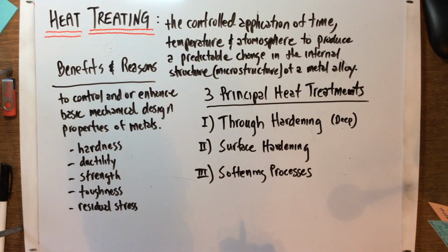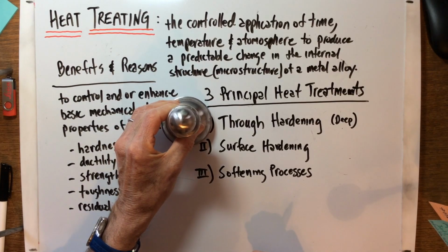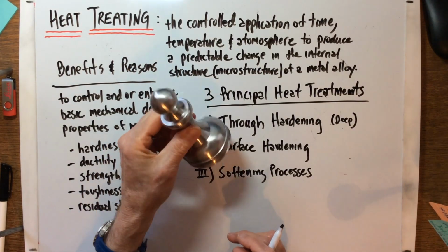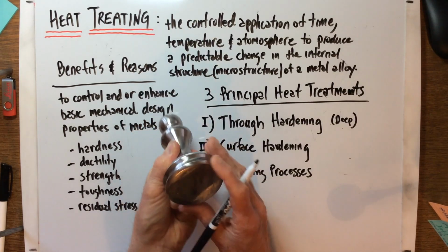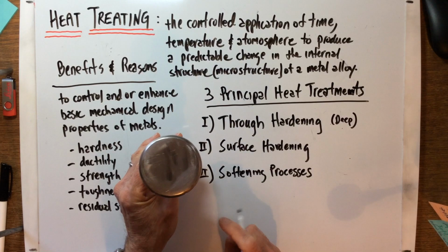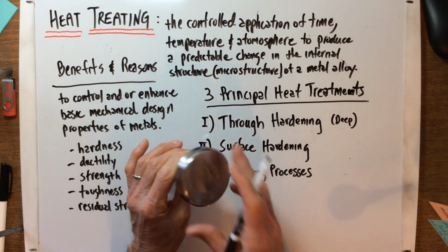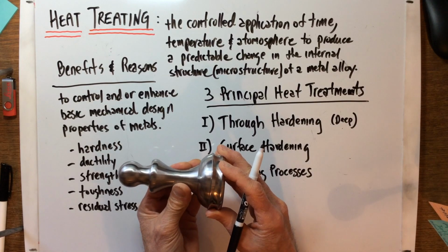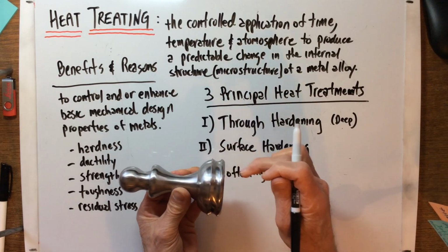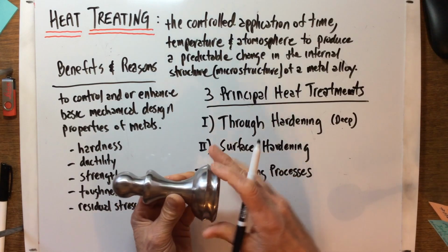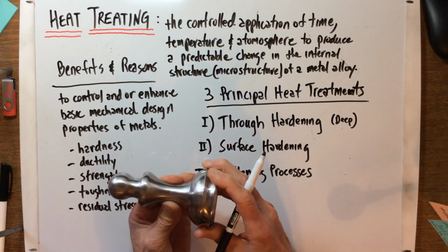But that essentially is taking something like this, a solid piece of steel that looks like this, and it actually started off as just a solid bar. Based on what we talked about this morning about machining, we put this in more than likely a CNC turning center, and we removed all this metal from that solid bar to get this geometry profile, this shape.